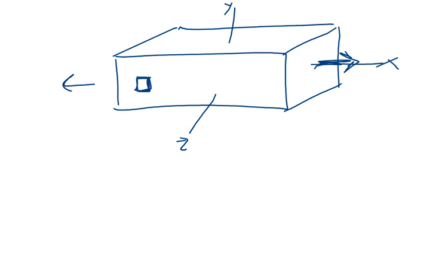And now you can imagine what happens to the square once you apply that tension. It stretches into a rectangle. And you can see there are no changes in angle. All the right angles stay right. So you get purely sigma and epsilon. You get normal stresses and normal strains. But that's just because I define my coordinate axes in that way. Okay, let's change things around.